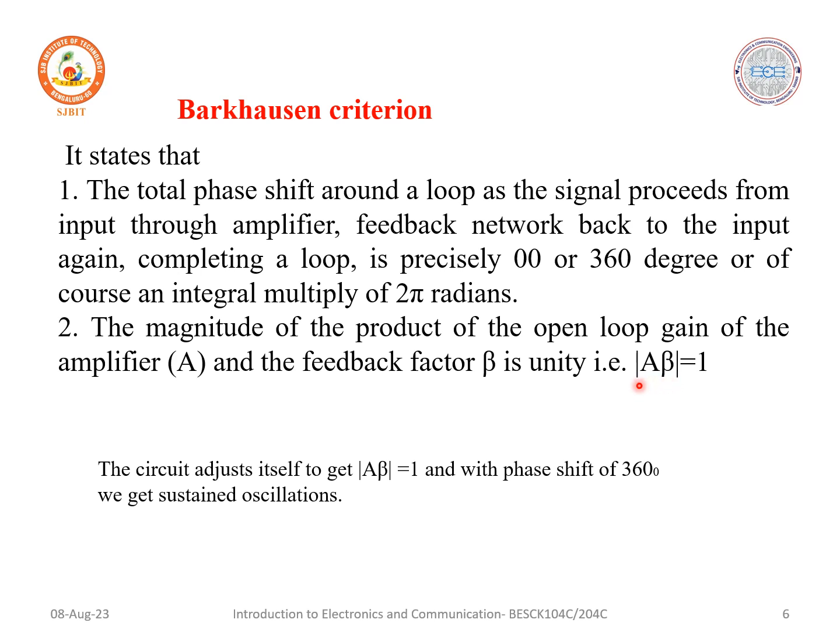A is the amplification factor, beta is the feedback ratio, and that magnitude is equal to 1. The amplifier's gain must be sufficient to overcome the losses associated with the frequency selective feedback network, that is, A beta equals 1. A is the gain of the amplifier.